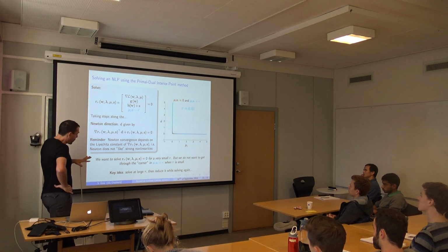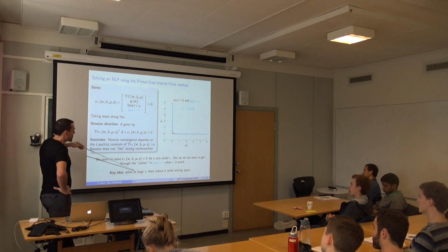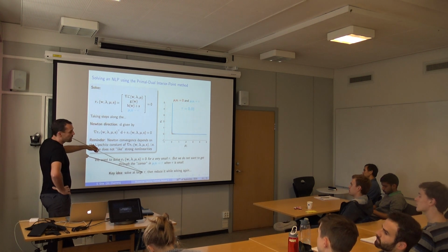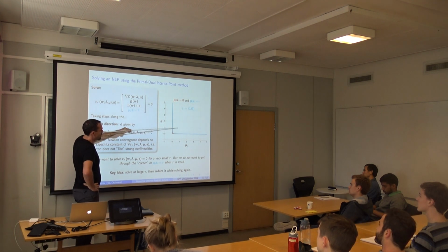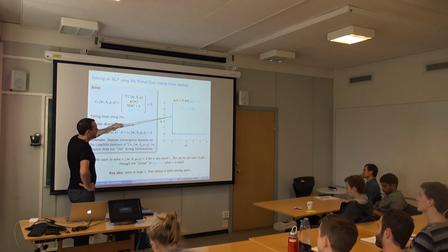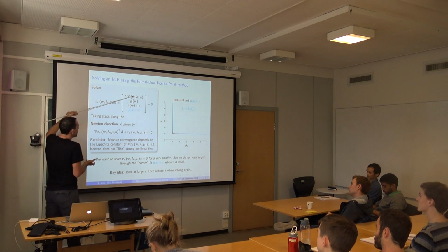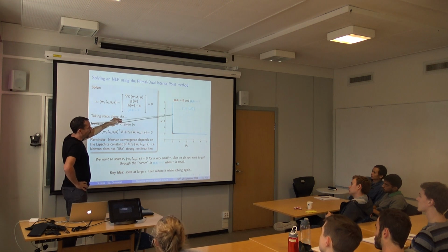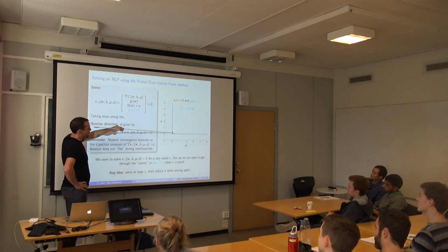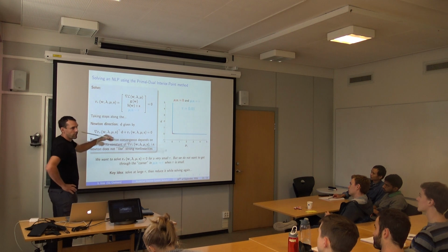The key idea that all solvers do to handle this thing again is you start iterating with a large tau, so you make a very smooth corner. If you have to go through it, it's no problem. It's gonna be very nice and gentle. And as Newton converges to r becoming small, you will decrease tau, make the corner sharper, and hopefully by the time the corner becomes very sharp, you are already on the correct side of your branches, and you don't need to bother about this corner anymore.